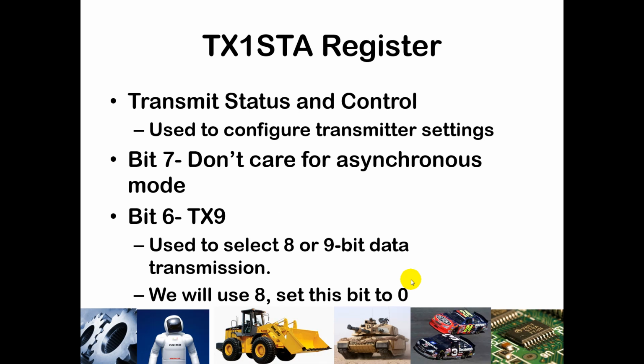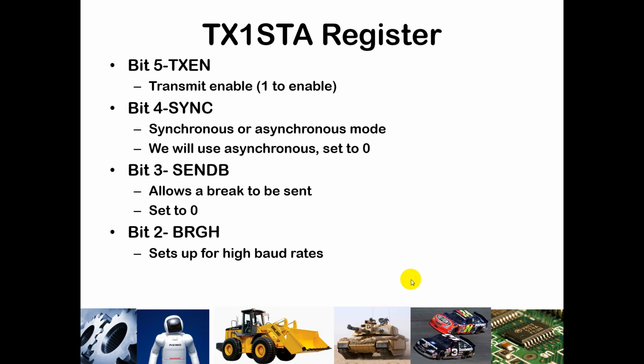The TX1STA register is an important register in terms of how this transmit of data will occur. And so this is basically just the status and control. So it tells you a little bit about how things have gone, and it tells you about how you are going to be transmitting data. Bit 7 is a don't care in asynchronous mode, so we won't worry about that. TX9 determines whether we're transmitting 8-bit data or 9-bit data. We're going to use 8, so that bit will go to 0. And then bit 5 is our transmit enable, and so in order to transmit anything, we will need to make that a 1. If we are going to be on the receive end, we will make that a 0.